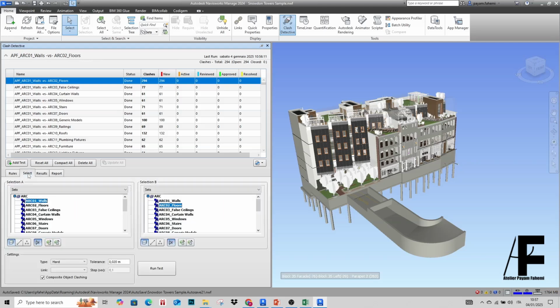So if I come over here, let's make some changes in terms of settings. For example, this Self Intersect button: if I deactivate it for each element, you can see a yellow triangle warning sign, which means that you made some changes in this set.